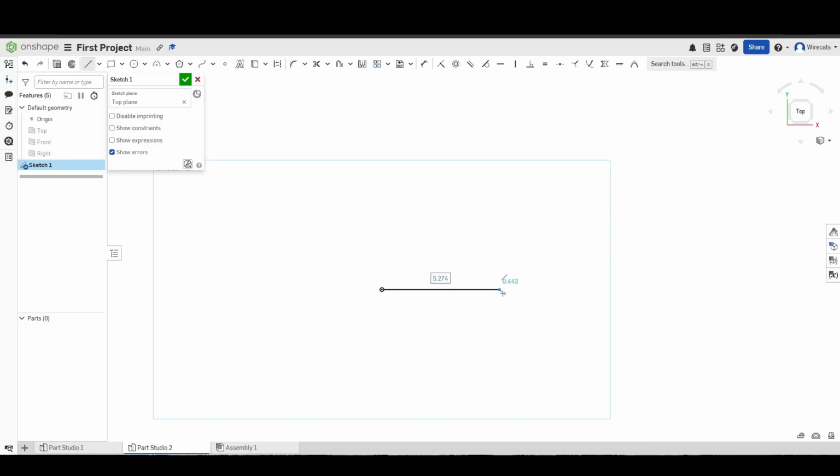And if I don't want to use the dimension tool manually, you'll see that this little 5 right here is automatically in this box. And right now, if I just start typing, you'll see I start filling in that box. So I'll put an 8 in that box, for example. Okay, and I'll hit the escape key. Now I have a line that's 8 millimeters long.